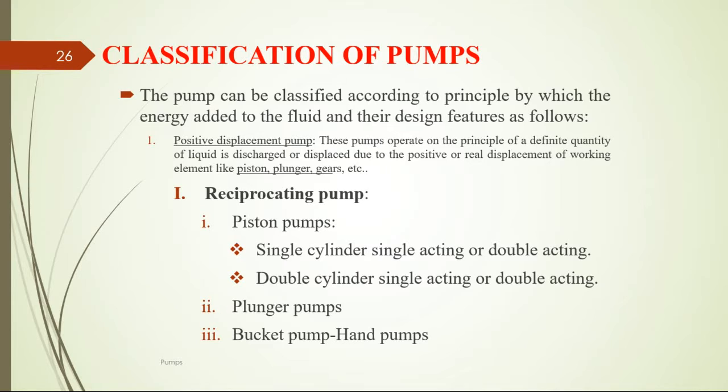The pumps can be classified according to the principle by which energy is added to the fluid and their design features as follows. First, positive displacement pumps. These pumps operate on the principle that a definite quantity of liquid is discharged or displaced due to the positive displacement of a working element like piston, plunger, gears, etc.